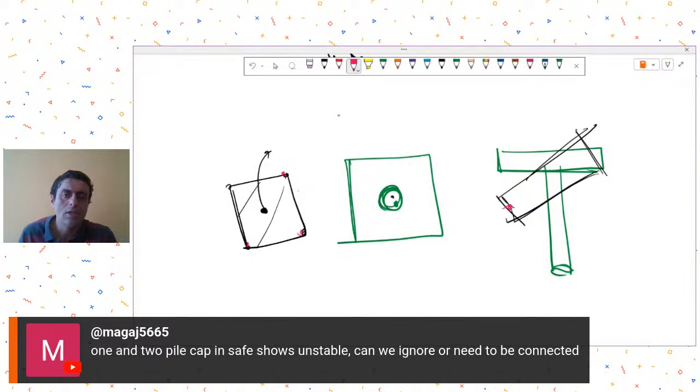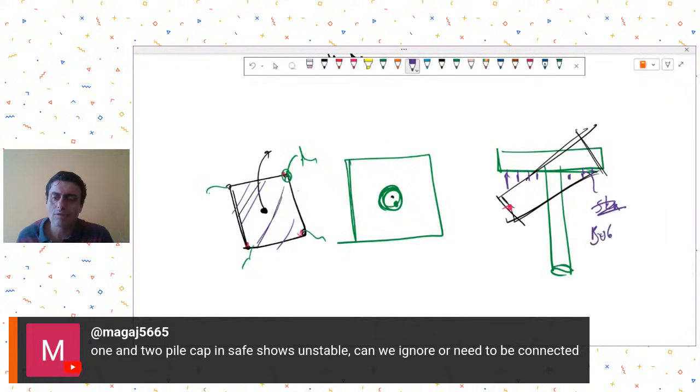So therefore you will see very large deflections at these points in SAFE, and then we get confused about what is happening. So what you can do in such cases is provide translational restraints to these four corners, and maybe you can also provide some subgrade modulus to this area element. That subgrade modulus may correspond to, let's say, 50 to 60 kilonewton per meter square SBC.